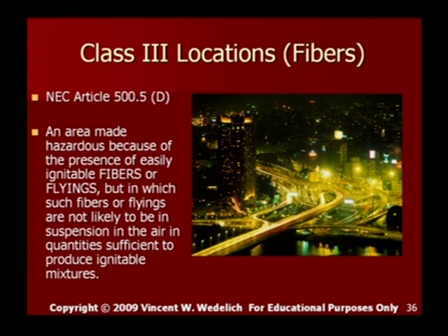Class 3 locations, fibers, and NEC Article 500.5D: an area made hazardous because of the presence of easily ignitable fibers or flyings, but in which such fibers or flyings are not likely to be in suspension in the air in quantities sufficient to produce ignitable mixtures.